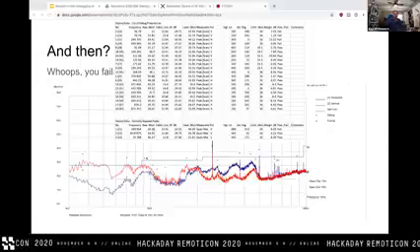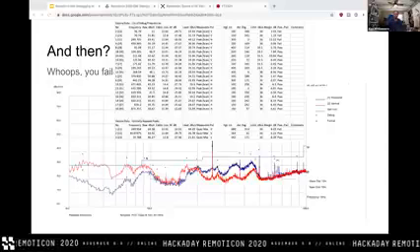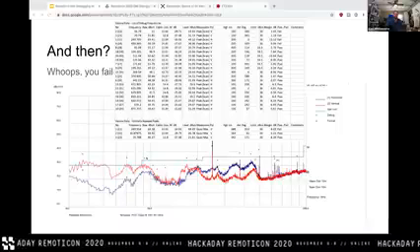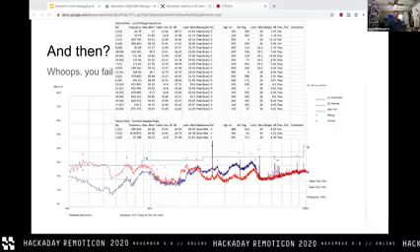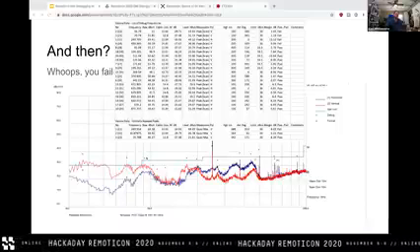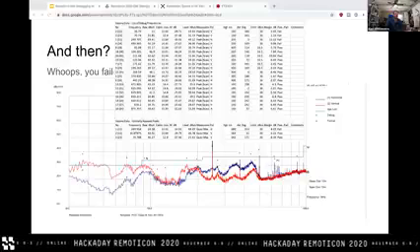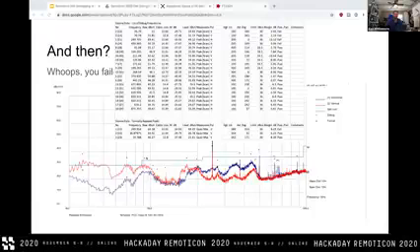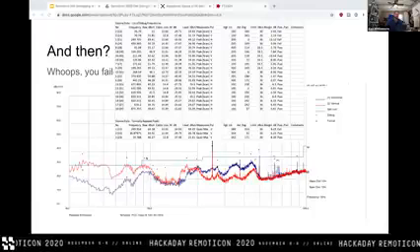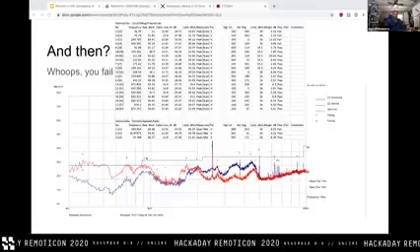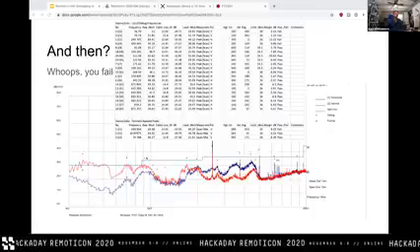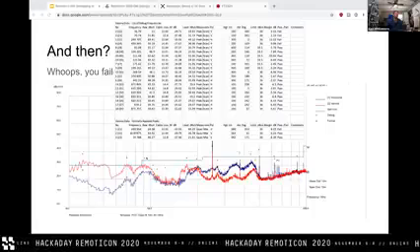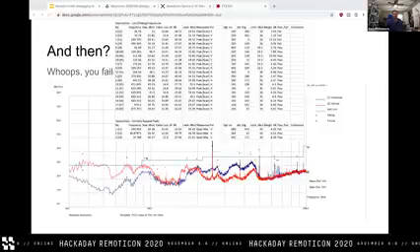For those of you who know what you're talking about in RF, this is about the edge of my experience and knowledge here, but the gist of it is that the first pass of peak detection gives you an idea of where to look for potentially offending and failing signals, and then you go back and do what's called a quasi-peak analysis, or rather quasi-max power analysis. I don't even know if I'm saying that right, I'm sorry.